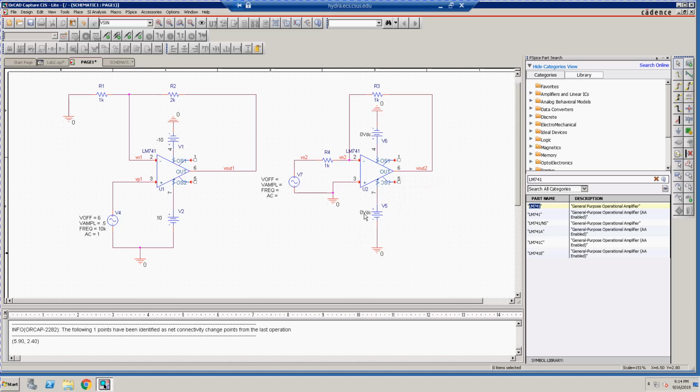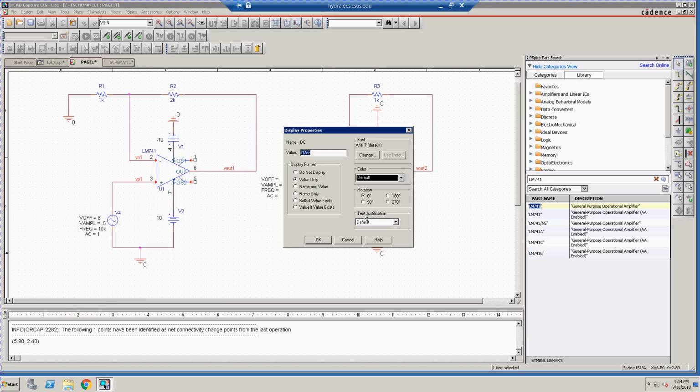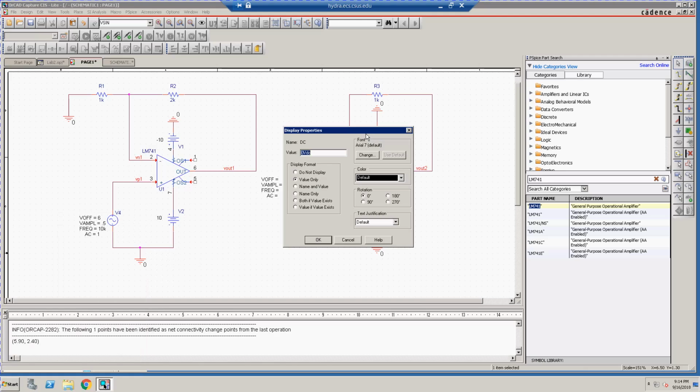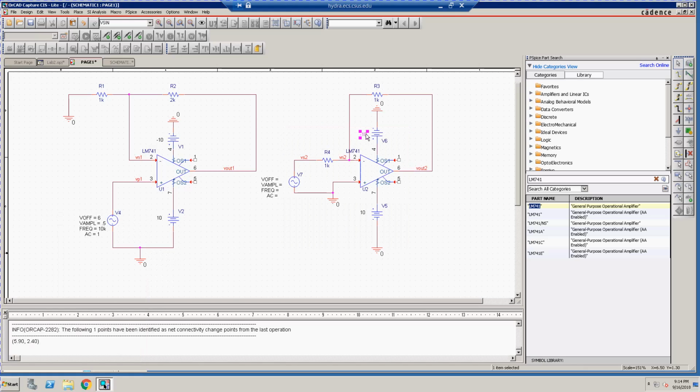Okay, so to change the voltage value, we simply double click on the 0 VDC. Just going to enter a 10 in. You don't have to enter the V. And that creates a 10. Then we come up here. Keep in mind, our negative source has to be at negative 10 volts. And again, you want to pay attention to the orientation of the source, with the positive being here, and the negative to ground. We want this to drop 10 volts. We have negative 10 here.